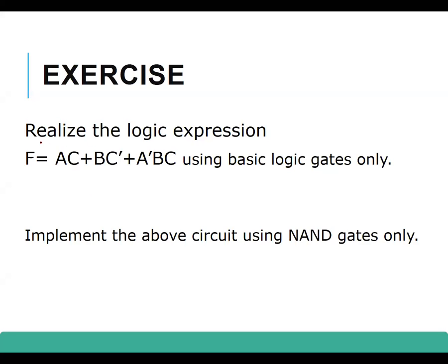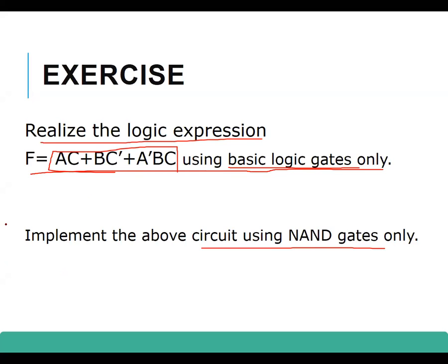So first you have to realize the logic expression given here using basic logic gates only. When you're drawing this, first use only basic logic gates and then implement the circuit using NAND gates only. I'll give you a few minutes so you can draw that.